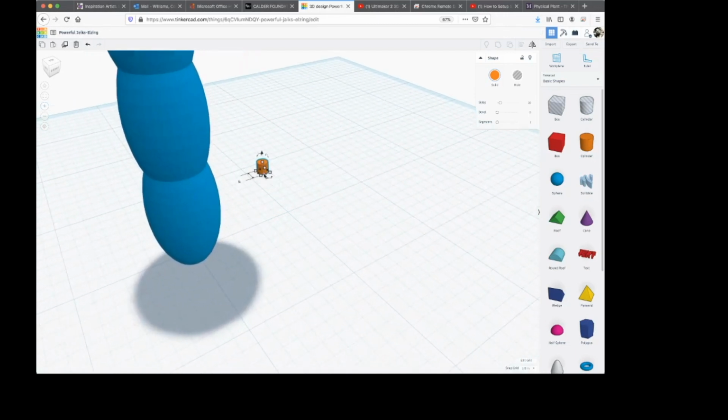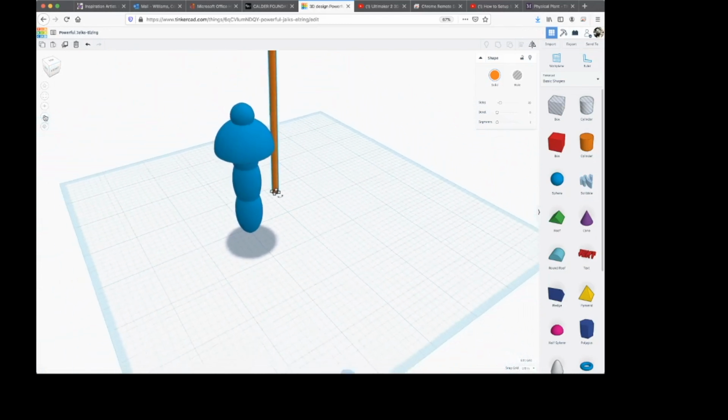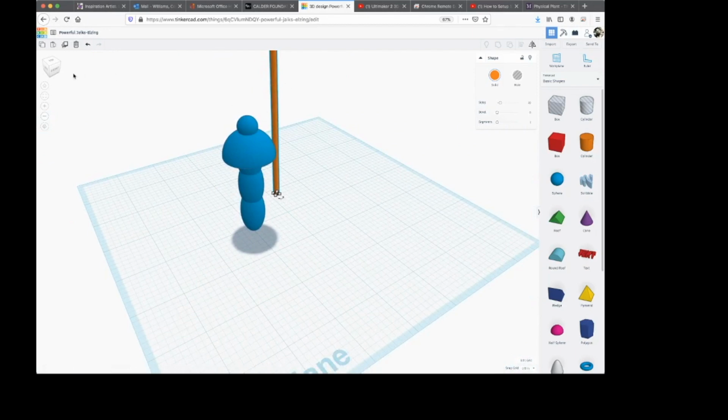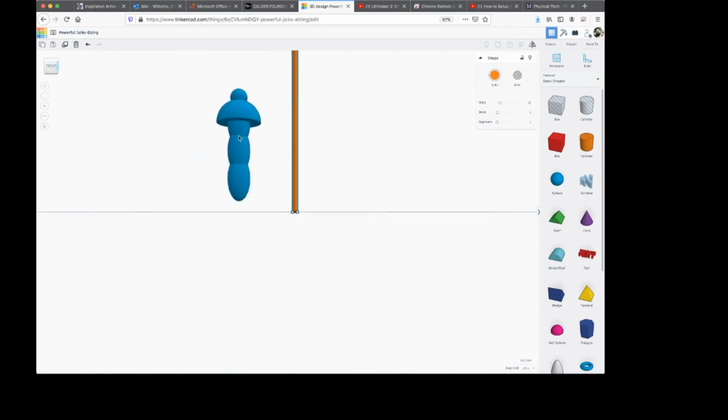Let me look at that. Yeah, that's 1/8 of an inch. So that'll be a good size hole. Now, I need this to be the height of the blue form, okay? So I can get that top handle, and let's change that from 1/8 to maybe 5 inches. Let me see if that may not have been enough, but let's look. Oh yeah, that's plenty. Okay, I just want it to be longer than the blue form that I made.